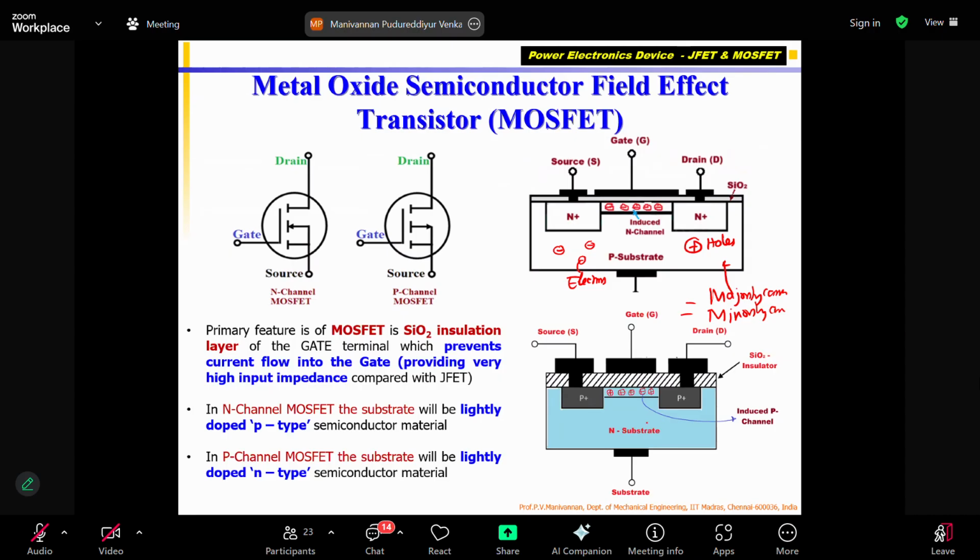Similarly, if you take N-type material, correct, the majority carriers are electrons. Everywhere electrons are there. I said 100 electrons. I have doped phosphorus, 100 atoms, replacing 100 silicon atoms out of 1000 atoms. So my N-type material has electrons as the majority carrier, because I have added phosphorus, but it will also have a few holes here and there.